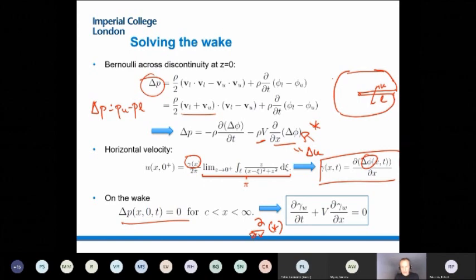Okay, what that tells us is how much is gamma w based on how was somewhere upstream. In terms of the physics of the problem, wake becomes a history of past change of circulation that happened on the airfoil. Every time you shed circulation from the airfoil, it gets convected downstream on the wake, and that information is preserved by the potential flow assumptions.